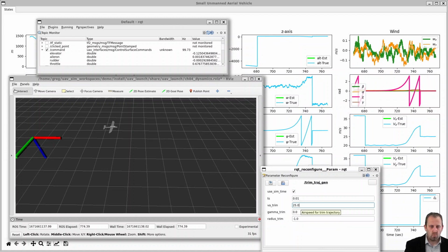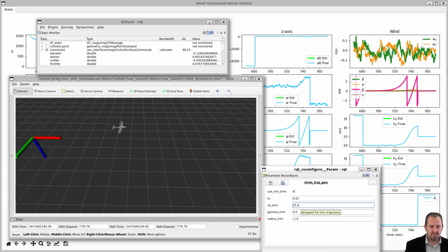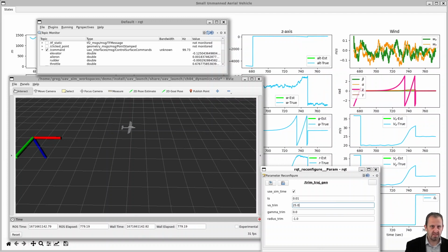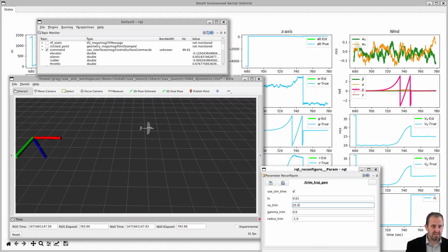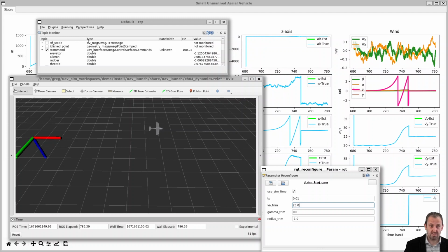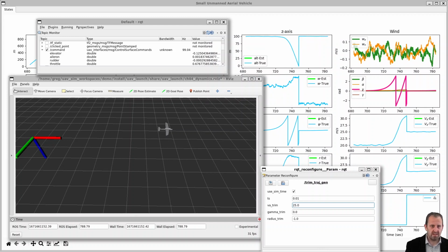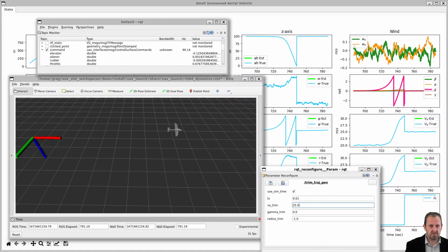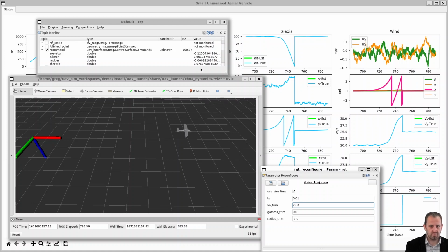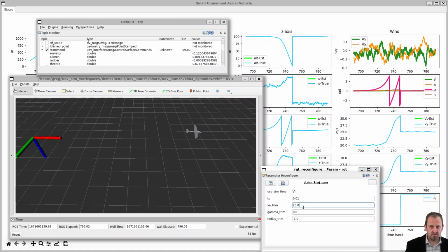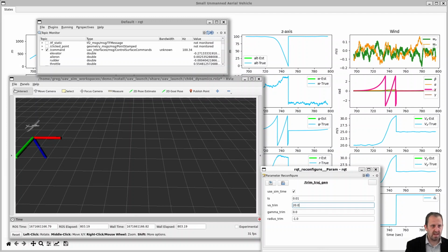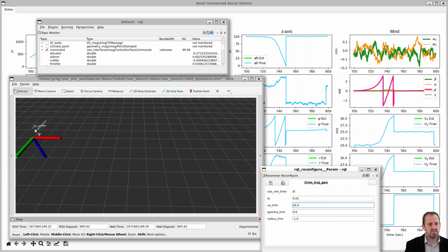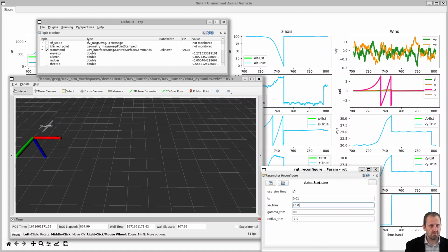And when we develop these trim trajectories, it produces steady state inputs that we can apply to our system. If we apply that to our system at the particular desired state, then it'll stay going along a desired trajectory until perturbations knock it off course. And so this is really great. We can put in different values there, and you'll see now, as we're going slower, we need to pitch a little bit more to try to stay in that straight line motion.